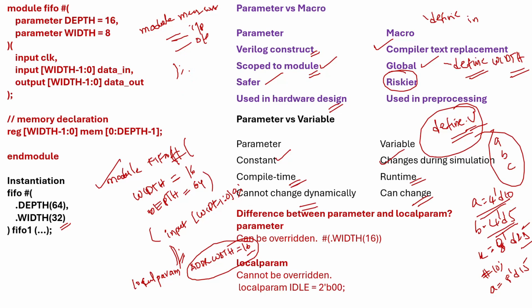Then the module's global parameters will be utilized in this memory controller, but the local parameters are not utilized in this module. Clear? Global declaration and local declaration: local means you can utilize it in the same module only, and in other modules you can utilize only the global parameters, not the local parameters.